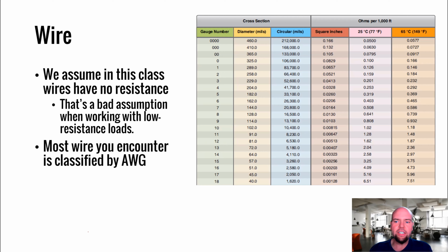The sizing of wires is typically AWG, which is the American wire gauge. It's our metric for the size of wires, and it doesn't follow any sort of SI unit standard. But for just casual wire use, it tends to be fine. And this is a chart here of gauge number of wire. So this would be called 4/0 gauge wire. That's a very large wire. You typically would only see that in industrial settings.